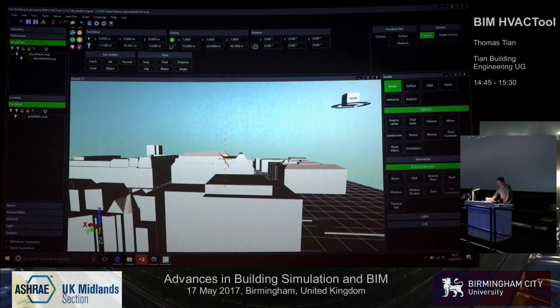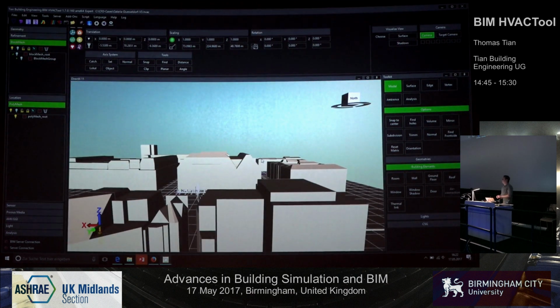Just one question. When you do the EnergyPlus simulation, is that predominantly just to get all of your boundary conditions, or are you trying to do other things with EnergyPlus as well? For OpenFOAM, the first step I need is the heat flux and the surface temperature. So it's a space load calculation, but not an energy calculation. For OpenFOAM, I don't need the rest. So only surface temperature and heat flux is enough.